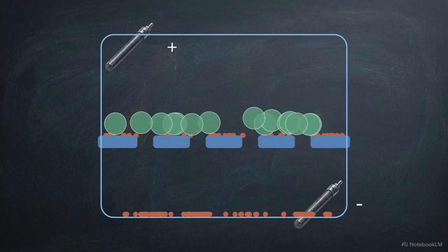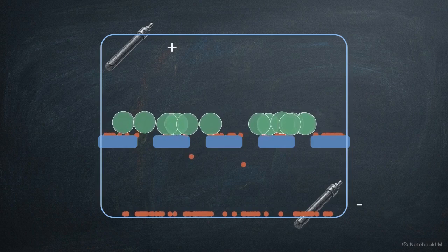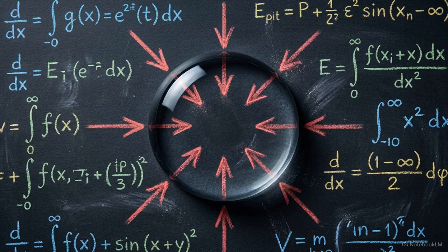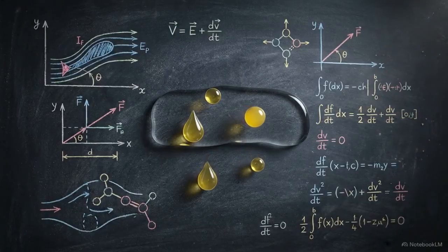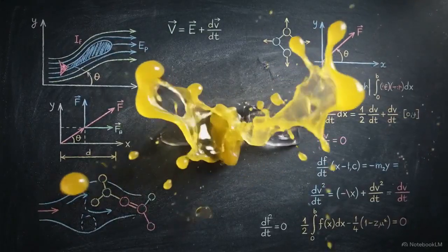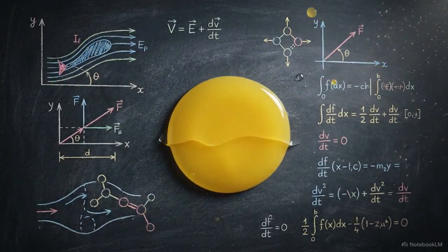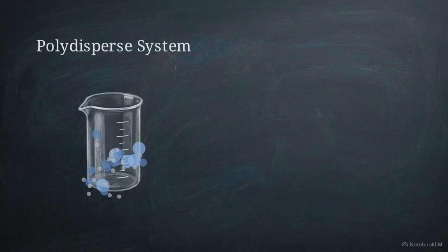However, membrane pore size alone cannot guarantee particle retention. Charged particles often repel the membrane entirely or adsorb directly onto the surface and block the pores. Creating a dispersed system requires forcing matter into a highly unstable state, maximizing its surface-to-volume ratio. Without rigorous purification and the immediate addition of stabilizing agents, those particles will rapidly reassociate to reduce their surface area, destroying the system. This diagram outlines the statistical math required to measure disperse phases, which inherently contain a wide distribution